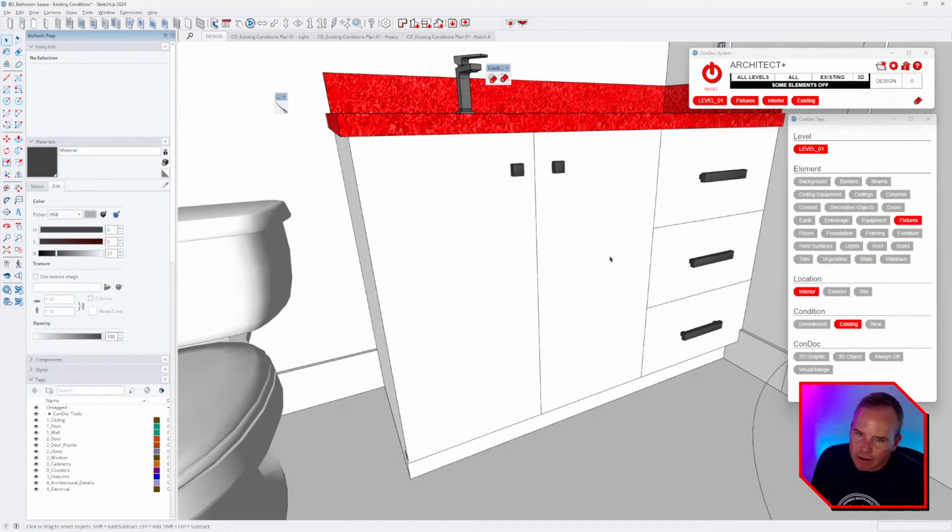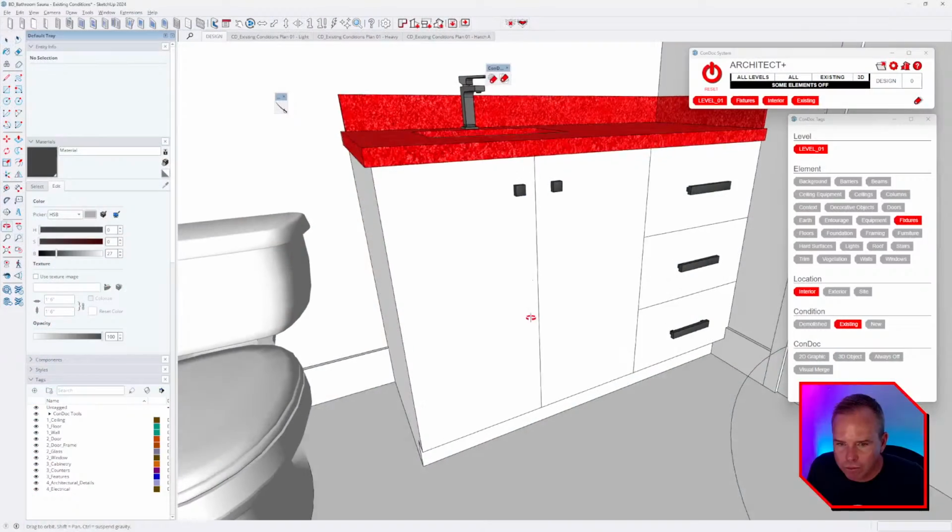All right. And then like I was saying, those cabinets aren't going to render properly. Although I will say this, if you add the gaps between the different panels and things and drawers, it's going to end up being kind of heavy on your interior elevations. But if you're making renderings, those aren't going to show. So for us, we'll make our interior elevations at a bigger scale. We'll go to like 1/2 inch, and that way the line work won't be so heavy.